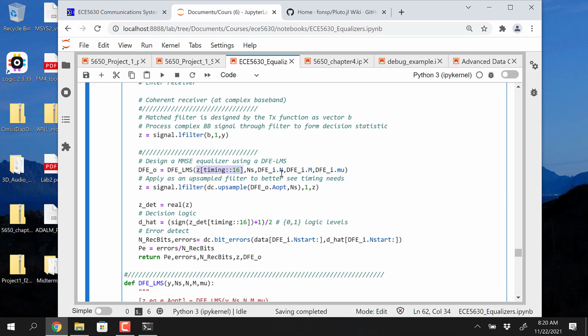Because one of the things they didn't talk about, which is in the books, it's probably in that chapter actually, the chapter that I put from that book on Slack, the fractionally spaced. It's like aliasing. When you only sample once per symbol, there's information that gets folded because you're downsampling, and you're going to create aliasing for sure. But that's the nature of the symbol-spaced equalizer. You get the best samples you can, and then you have some aliasing that takes place.